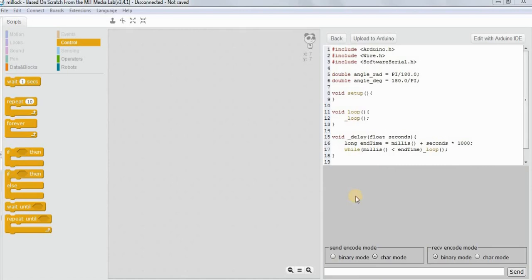So when we are calibrating our sensors, we want to know what value we get from sensors at different conditions. For example, if I have a light sensor, I want to know what is the value I get when there is light and what is the value I get when there is no light. And even if my light sensor is an analog sensor, I need to calibrate the reference point.